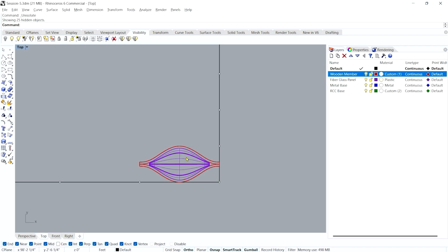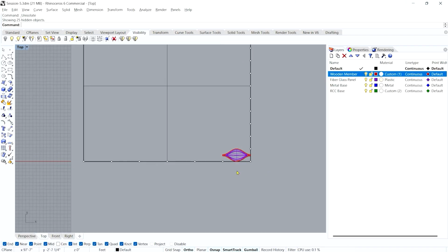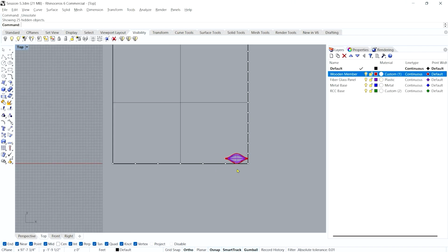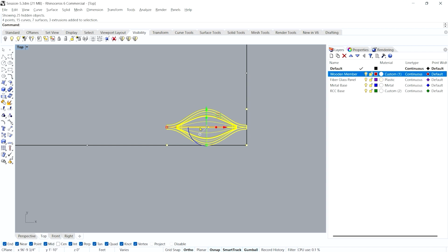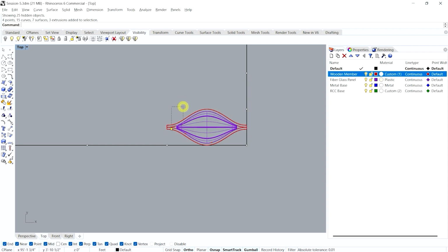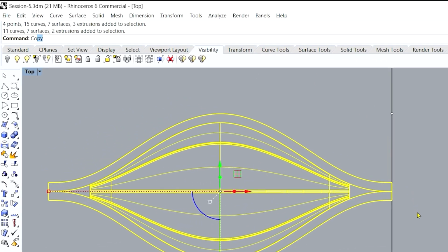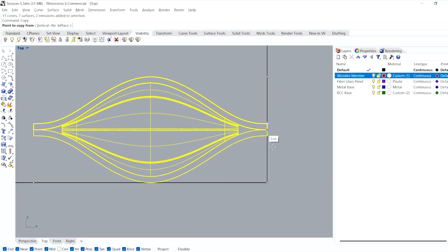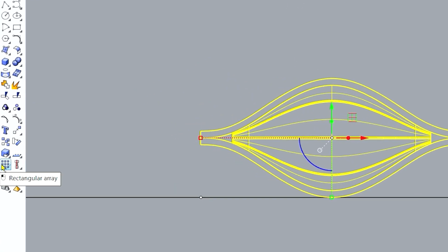This one single element. Now the only thing I have to do is copy it multiple times. So I will spread this element all around the grid first of all. So let's select it and start copying. I will select these two objects and copy, or you can use the array copy command, rectangular array, which is also a good way for a faster copying method.